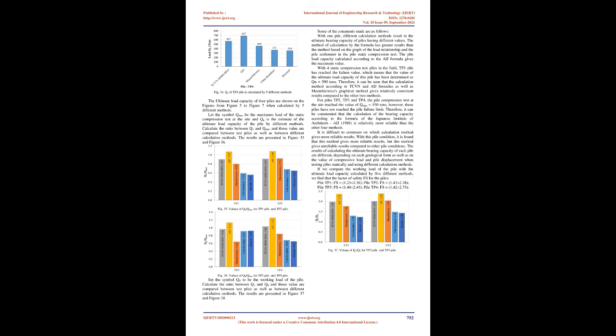It is difficult to comment on which calculation method gives more reliable results. With this pile condition, it is found that this method gives more reliable results, but this method gives unreliable results compared to other pile conditions. The results of calculating the ultimate bearing capacity of each pile are different, depending on each geological form as well as on the value of compressive load and pile displacement when testing piles statically and using different calculation methods. If we compare the working load of the pile with the ultimate load capacity calculated by 5 different methods.